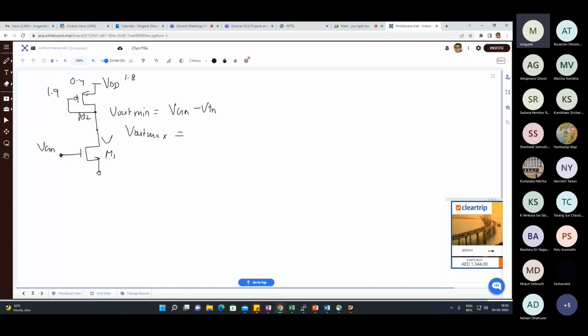You can still say this is operating in the subthreshold region, but the design equation, W by L of transistor M1 by W by L of transistor M2, with GM1 by GM2 cancelling out all other parameters, will no longer be valid, because beyond the value of VDD minus mod VTP, the upper transistor will enter the subthreshold region, and then those equations we had for GM will no longer be valid.